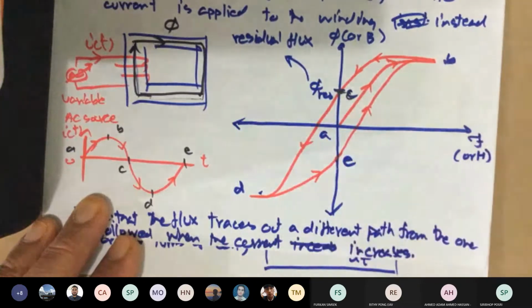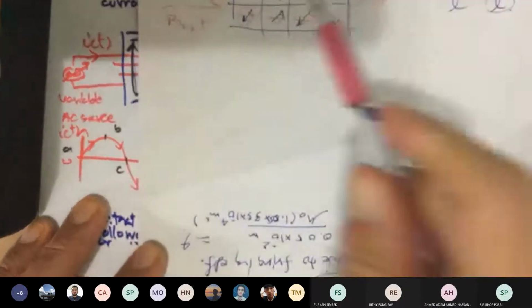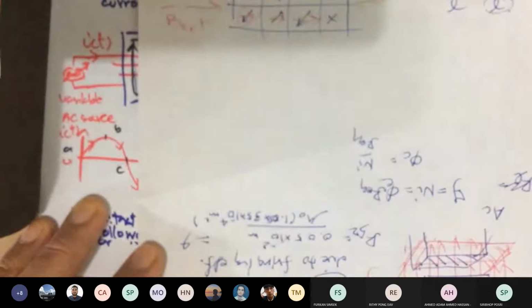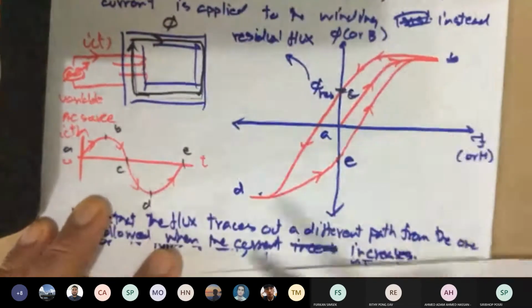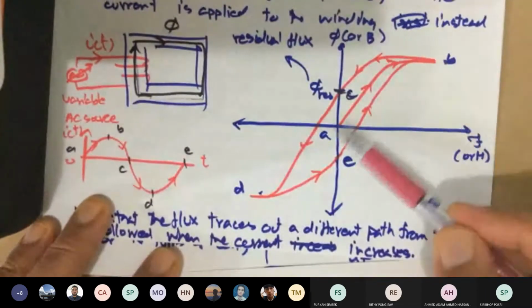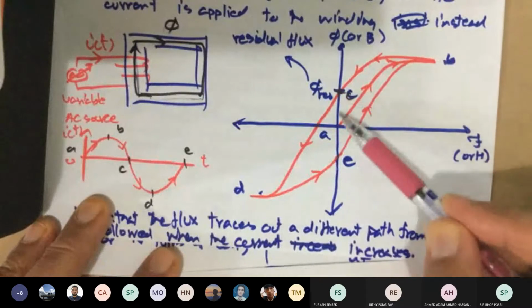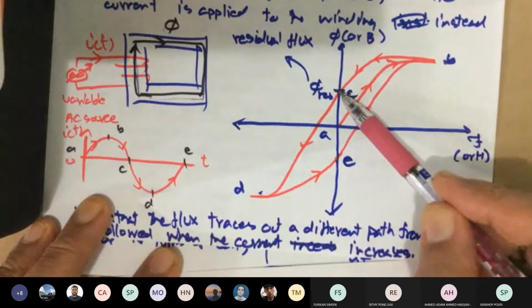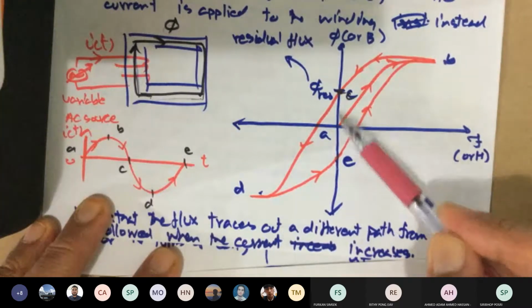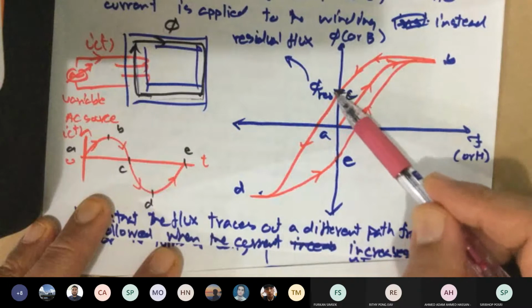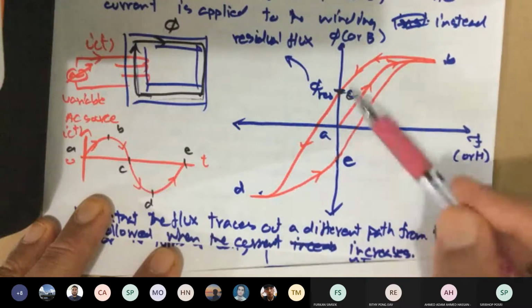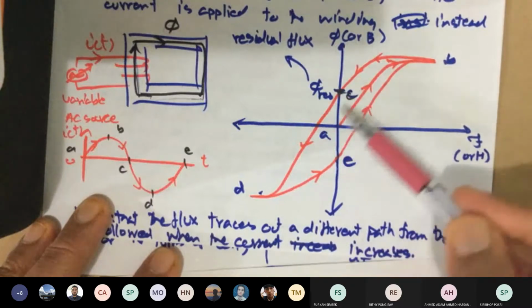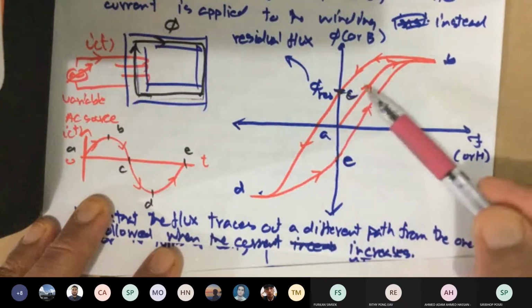Okay, so meaning if I have a piece of iron, I zap some external current into that and then take the current off, my iron becomes magnetized. Notice this path from A to B back to C, 0 current again, but now your phi is different. The initial condition was 0, now it's non-zero, residual flux. This is the principle that we use to make permanent magnets in industry.